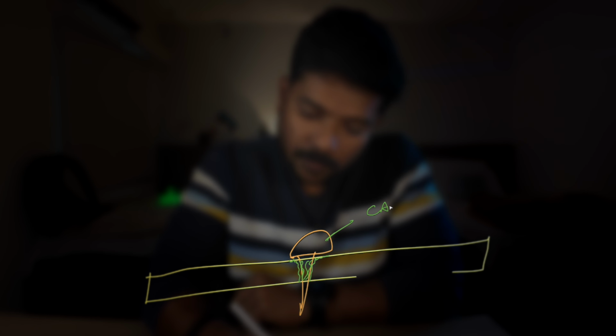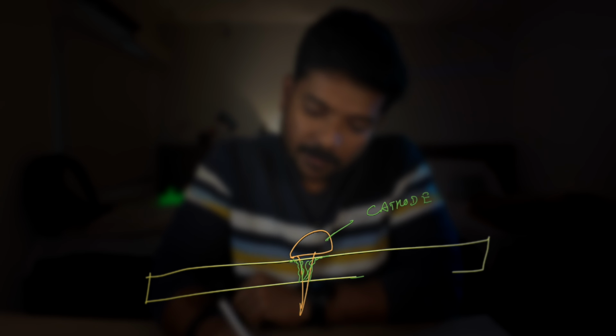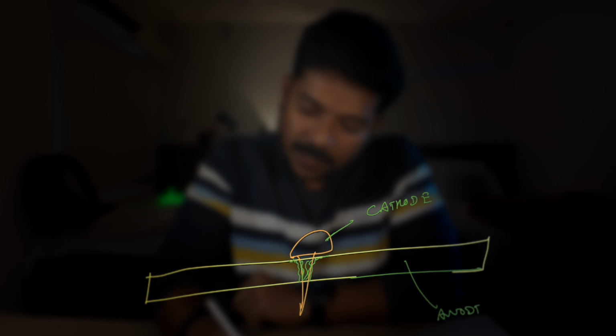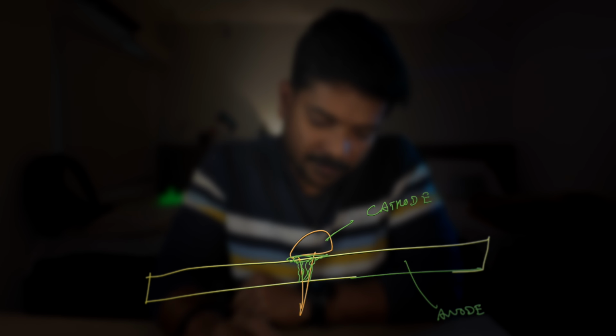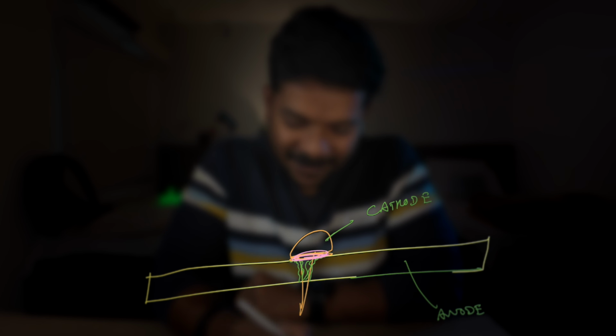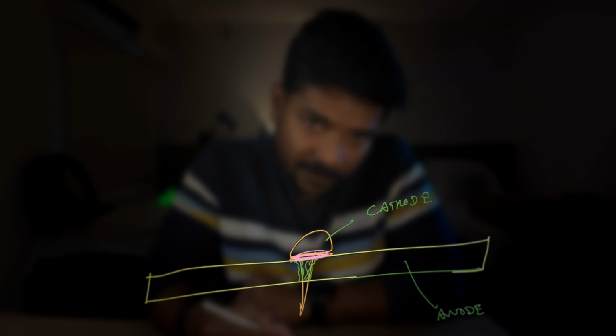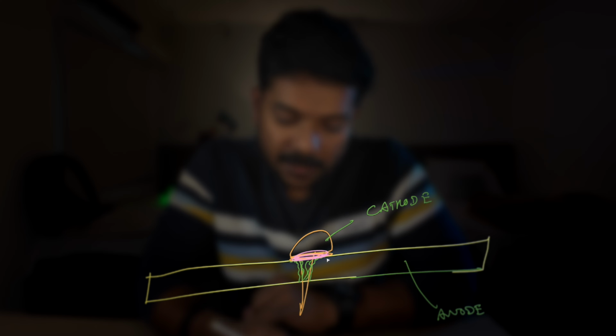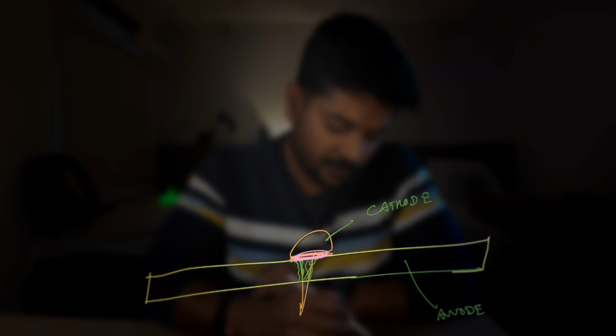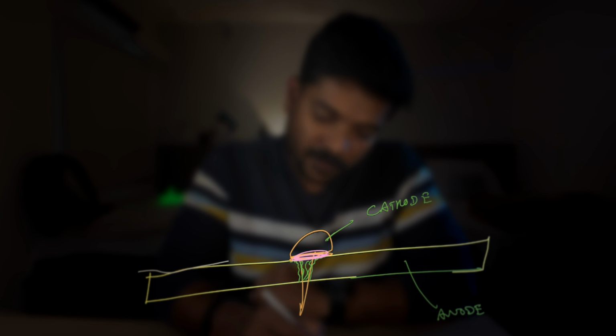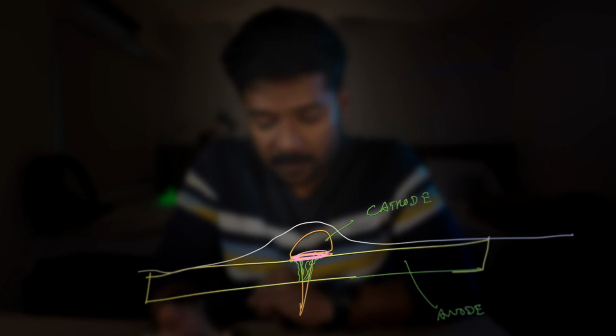Multiple lines of defense, that is an important factor. Redundancy of protection is a good idea. What I'm saying is, in the example that I just gave, this stainless steel screw being cathode and the aluminum cladding panel being anode, here we are using a washer, that is one preventive measure. We have used materials that are not too far apart from each other on the galvanic series, that is another preventive measure. We can, say, provide a waterproofing membrane on top of it, that is a third preventive measure.